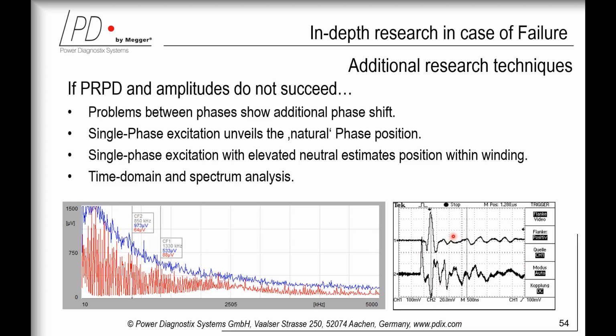Last but not least, the spectrum analysis can also give information about the signal position. A missing high-frequency component is a strong indicator for a signal originating deep within the transformer, since the higher frequency components suffer more strongly under attenuation effects, as stated before, than the lower frequencies.